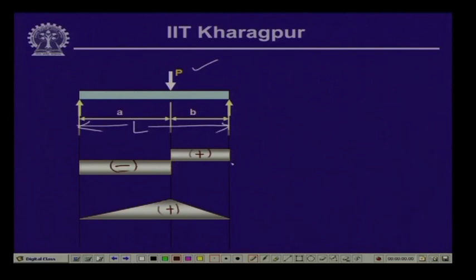So this we have taken as our abscissa, the direction of the beam, and these are the ordinates. This is the positive direction and this is the negative direction, and here again this is the length of the beam and this is the ordinate of the bending moment. The diagram over the length of the beam which we get, we call the bending moment diagram, BMD, and this we call the shear force diagram, SFD.